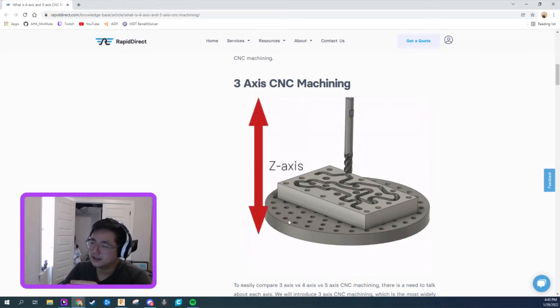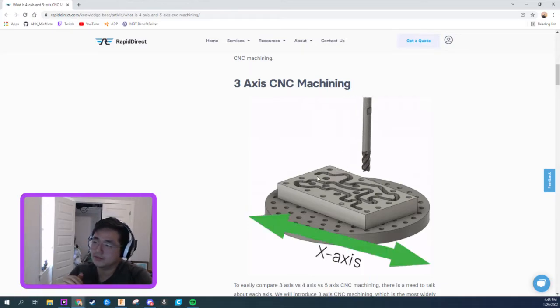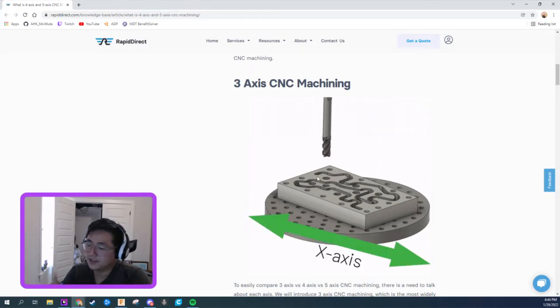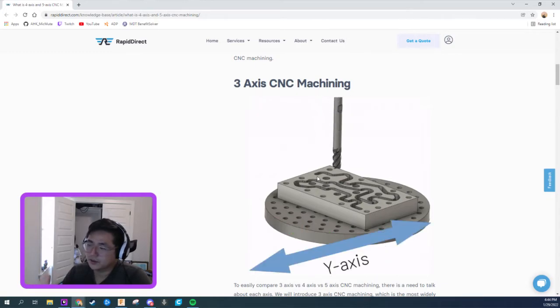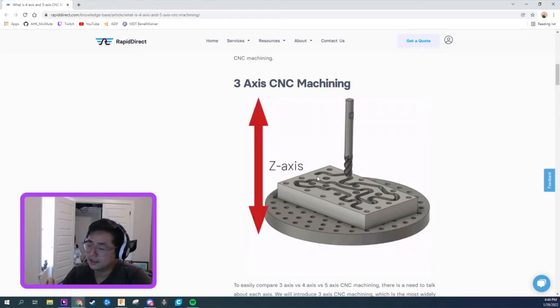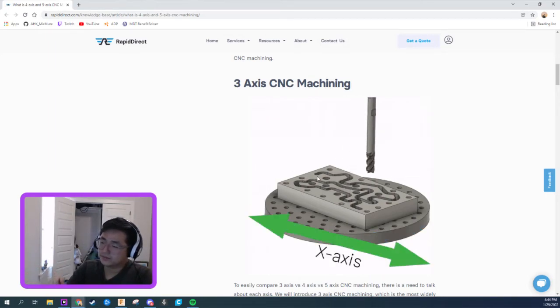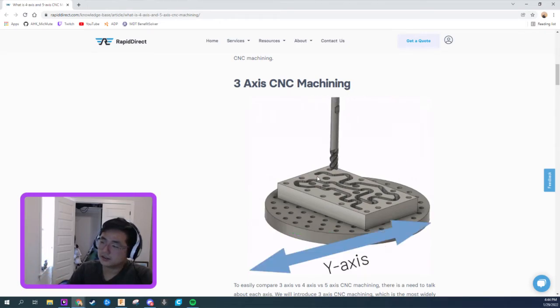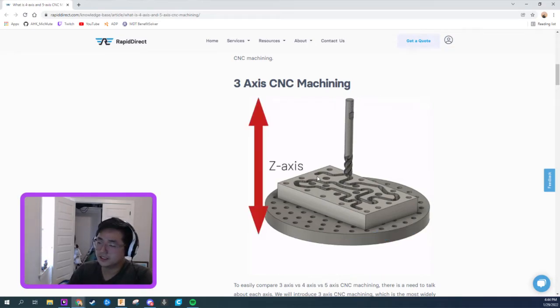Like Jonathan said, if you want to mimic that slope or curvature, there is that technique called sculpture milling where your tool can still move in the X, Y, and Z, and you can imagine that you can just draw curves with that tool along those 3 axes. So you're making parabolas or arcs in 3D space instead of just traveling along a straight line all the time.